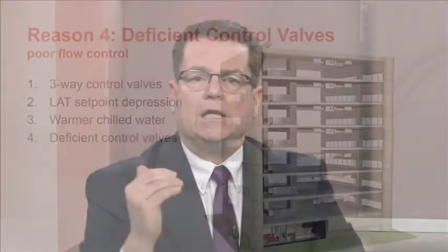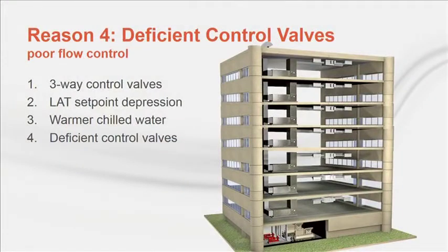This was driven home to me recently during work at a high-rise building in Atlanta. Each floor had identical air handlers and chilled water control valves. The chiller plant and system pumps were in the basement. Since the air handlers on the lower floors were closer to the central plant, they are subject to a much higher system pumping pressure than the higher floors.